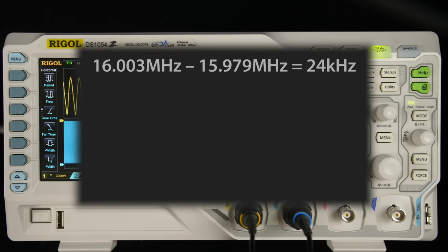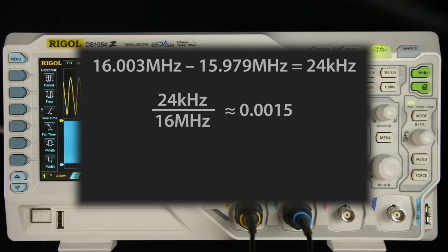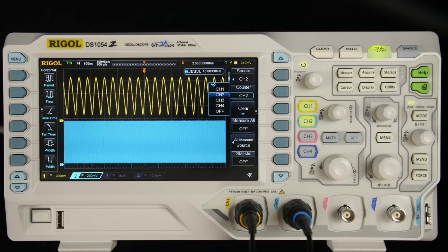Well, if you look at the difference here, it's about 0.15%. So how big a deal is 0.15%? Well, another way to look at that, if you take 1 over 0.15%, you get about 667. So what does that mean? That means if the transmitter is the faster one, which it is, then for every 667 bits that the transmitter sends, the receiver is only going to try to receive 666 bits. So that means we're going to get out of sync in under 666 bits. So that's obviously no good.